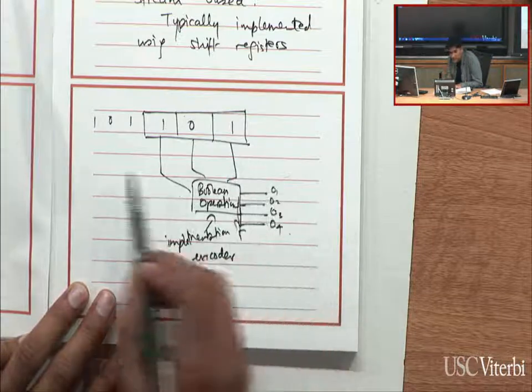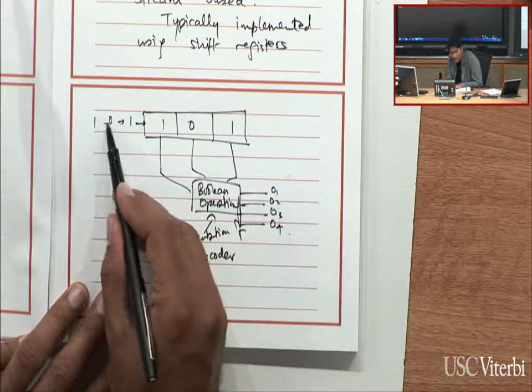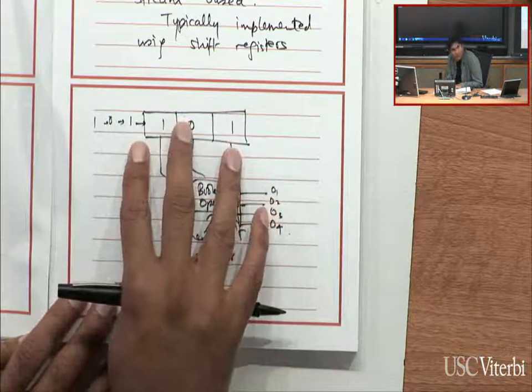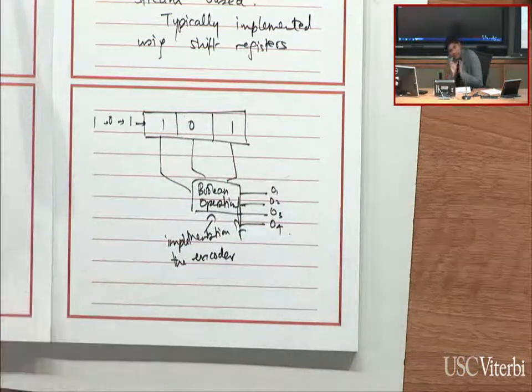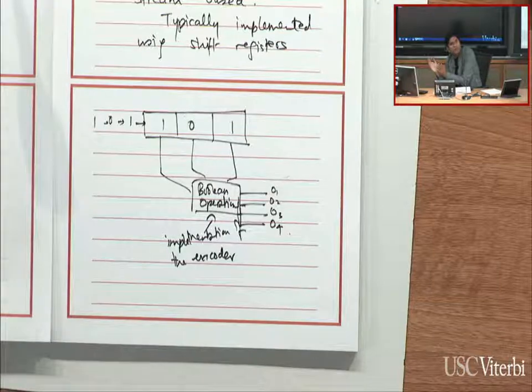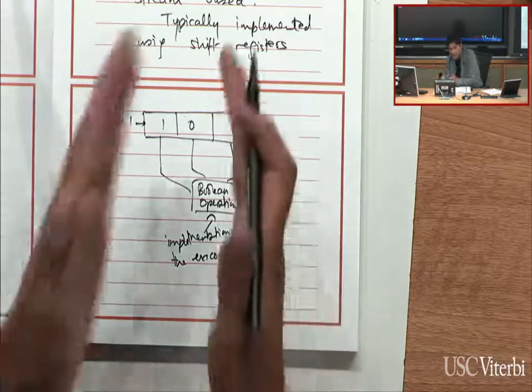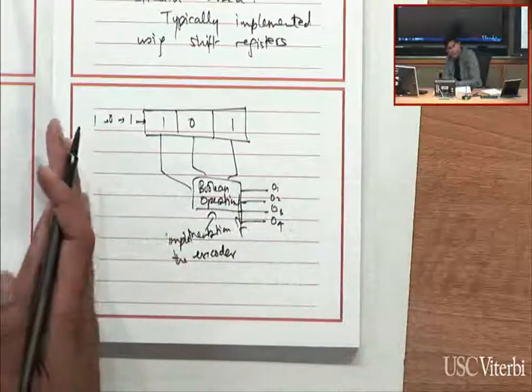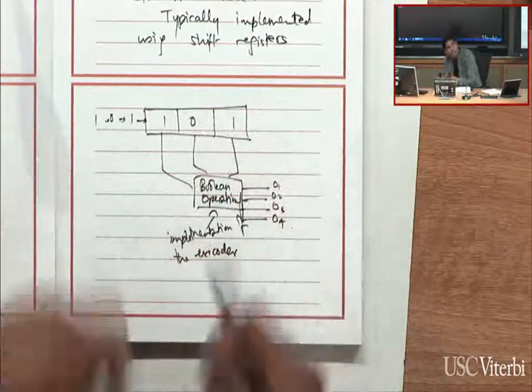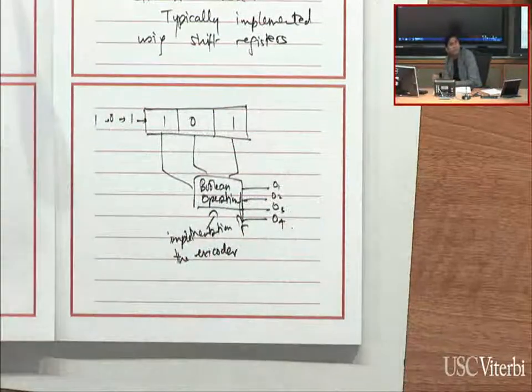Okay. And so the point is that which 3 bits you're operating on will be the 3 consecutive bits, and which 3 bits they are just keep shifting over time, right? And so it's not that we took these 3 bits, first encoded them, then took another 3 bits, and then encoded them, but rather as they keep shifting through, we keep running the encoder, and it keeps spitting out bits on the output.